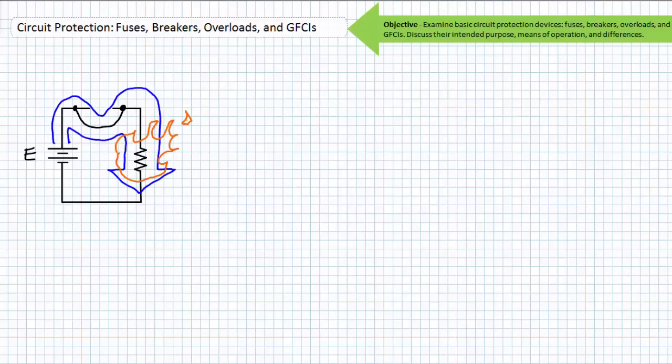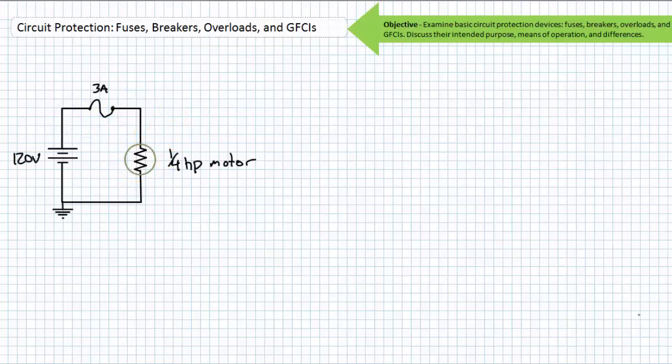Circuit protection exists for a reason. It is not to be bypassed. There's not a lot more to say about fuses except this. Fuses are non-reusable devices designed to protect the system from high current. They do not protect operators from leakage current.